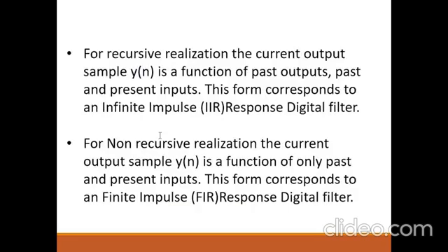Let us take a recursive realization of the block diagram representation. In the recursive realization of the block diagram representation, we know that in recursive type, the function y of n depends upon the past outputs, and past and present inputs. This form corresponds to an infinite impulse response digital filter. And for the non-recursive realization, the current output y of n is a function of past inputs and the present inputs. We know this from the equations.